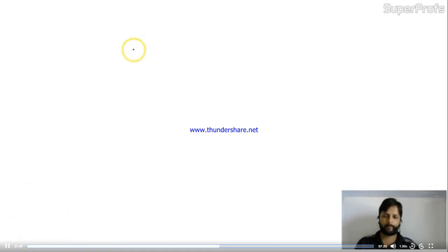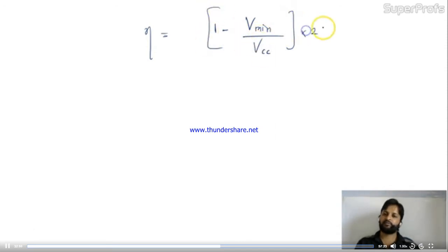So friends, the eta now becomes 1 minus Vmin divided by VCC into 25%, because 100 divided by 4 becomes 25%. So this is the efficiency given in percentage.